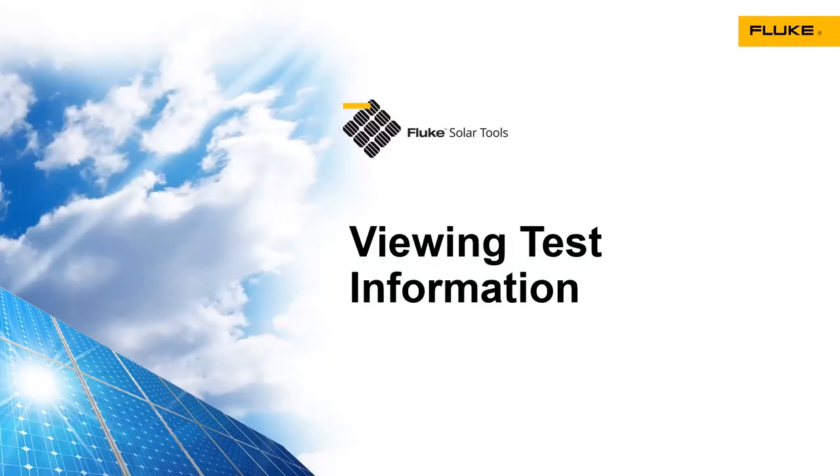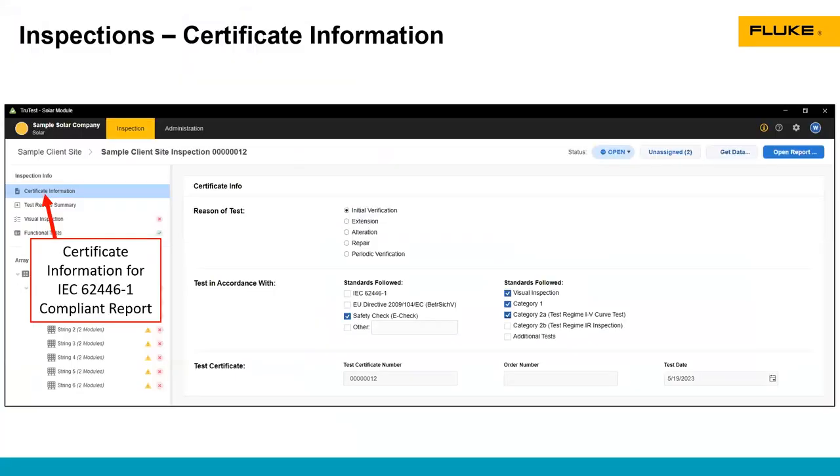Once you've downloaded data from the SMFT 1000 into TruTest, you can view the test information in the site inspection screen. The first thing we're going to see at the top left is the certificate information. The TruTest software and the SMFT 1000 are based on the IEC 62446-1 testing of photovoltaic systems standard. This is a requirement in Europe. It's not usually a requirement in the United States, but it's a really good guideline to work off of.